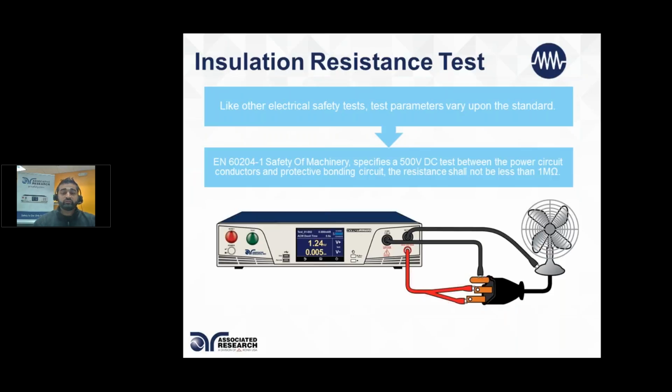than 1 megaohm. This is kind of generous, 1 megaohm, but we've seen it anywhere from 1, 10, even some that require more than 10 megaohms, 100 megaohms of resistance. So you see that the standards could vary on how much resistance is allowed for your insulator, but generally speaking, the higher the resistance, the better for the product's electrical safety, where there's no potential hazard at that point.